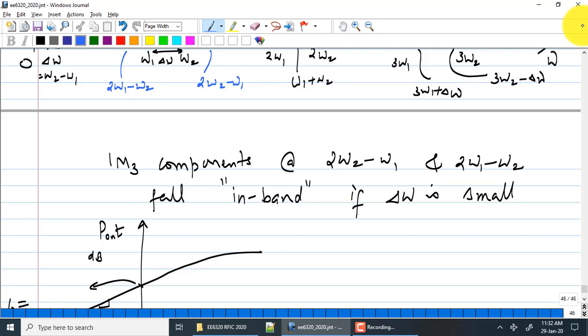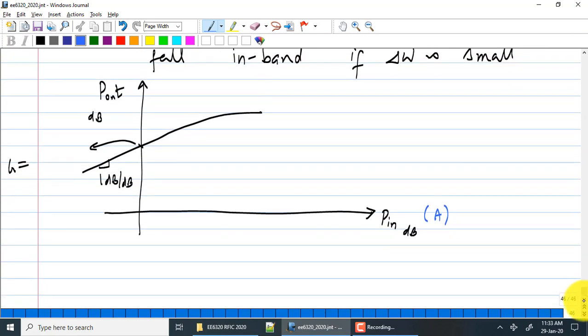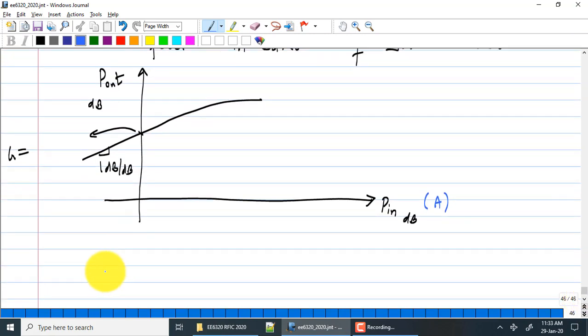I know that at very high amplitudes, the third order term itself will compress for sure, because I'll get components from the fifth order term, seventh order term, etc. Right? I don't want to look at that. In fact, in a couple of minutes, you will see that the definition of this type of nonlinearity does not care what those terms are. Now, I make A extremely small. So, I am now operating somewhere here. A is very small in this region, let us say.